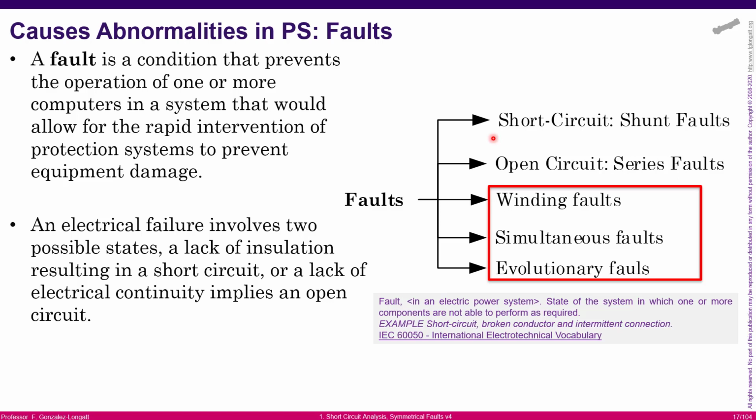That is what is happening in short circuits, and that is typically related with lack of insulation, or the insulation is broken. Okay. The other type is that we have discontinuity on the supply, and that is a serious fault. Okay. What I was trying to explain in short words is that the faults could be several types. Okay. They are what we call the shunt faults, and that is the topic today, short circuits.